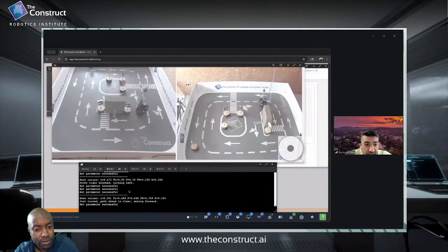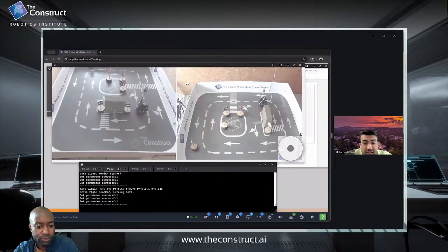So here, for example, we have the left distance, front left, front distance, front right, and the right distance. And our threshold is 0.3. For decision making, if the front, front right, and front left are blocked, it's going to start to rotate. Also, if the front is above our threshold, and all other parameters are also above the threshold, I make the decision to go forward instead of going in another direction.